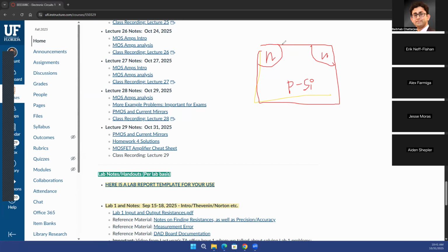That's a class that you can take on device fabrication, and you'll know how the MOSFET is actually created or how you do the ion implantation to create these N-type source and N-type drain, and then how do you create the gate in between. Now, for an N-type MOSFET, of course, you'll apply a positive voltage at the gate so that you attract electrons from the bulk as well as some of these electrons from the source and drain regions.